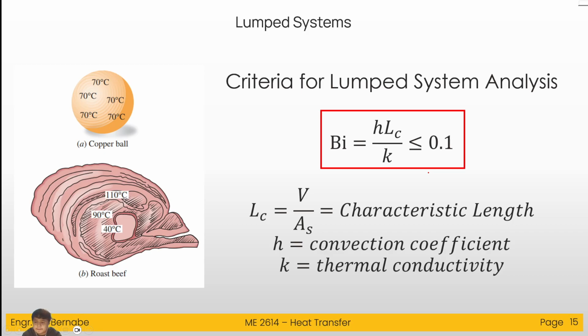Again, the formulas in the previous slides are only applicable when the Biot number is less than 0.1. So you have to compute the Biot number first before you can utilize the formulas given in the previous slides. Okay, so for the next video, I'll discuss the illustrative problems.